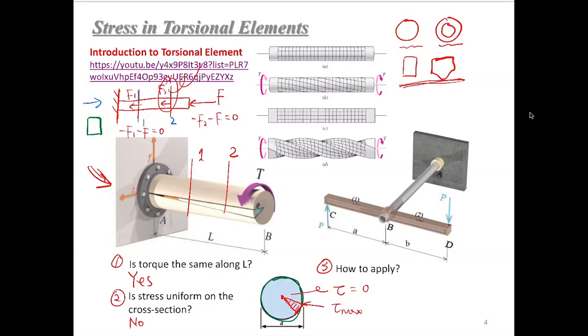As shown here, you can use arms and then add loads to them, so you will generate these moments. In this case, you have two arms and two forces, so you need to add the two moments together. That is the torque applied to this shaft. In later sections, you will see that we can also use pulleys or gears to apply torques to a shaft.